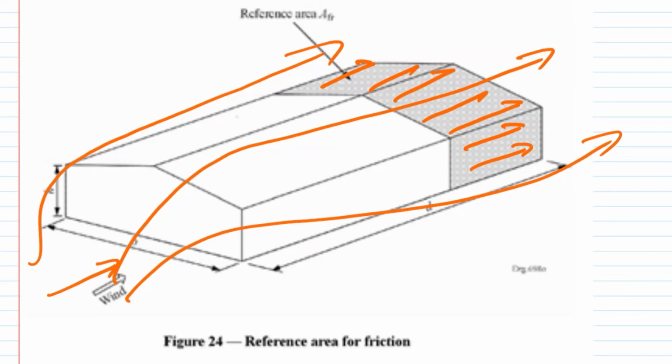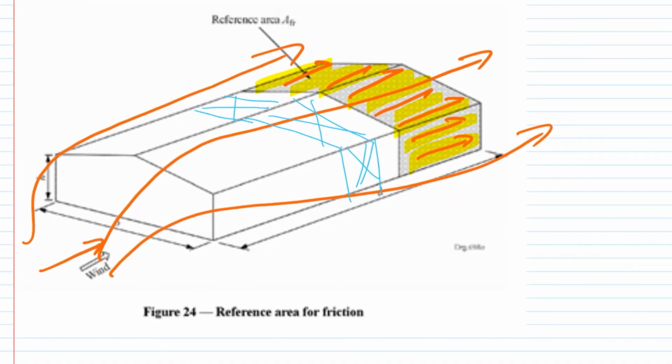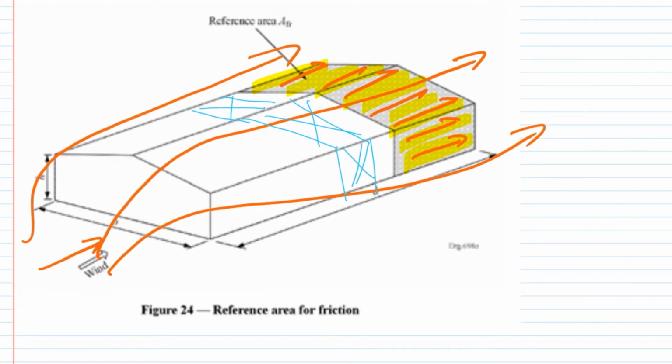For instance, you've got roof bracing here that's holding the structure up and providing lateral stability. This friction load will have an influence on it. So you want to make sure you account for that. So as I said, we're skipping this, but just remember, because of the wind blowing across the roof, you do get friction. You should account for that, but yes, we are ignoring it. But you would normally apply it over a specific zone, get the friction force, and add that onto your bracing system and make sure your bracing system can accommodate that.